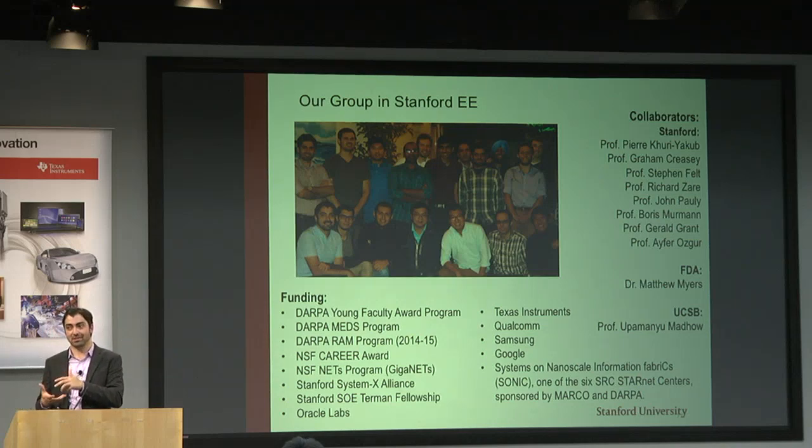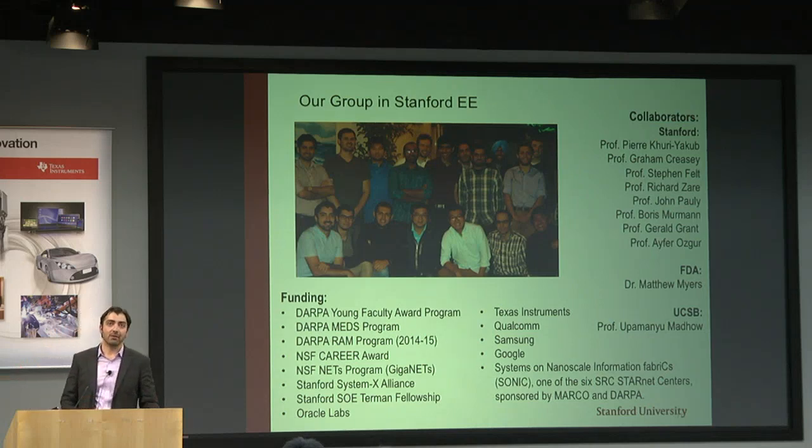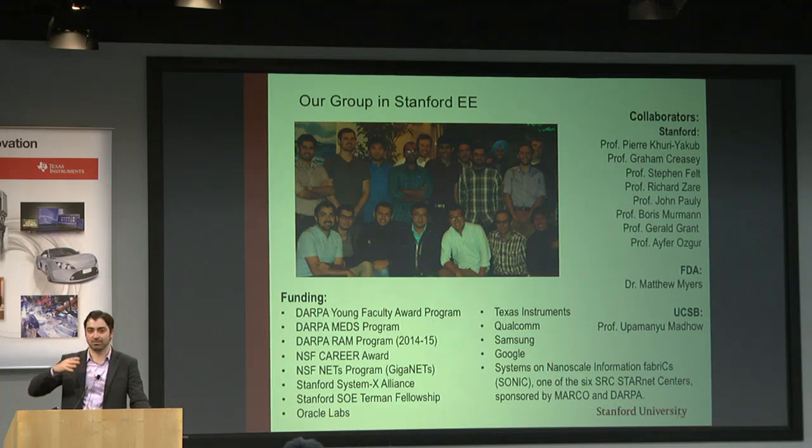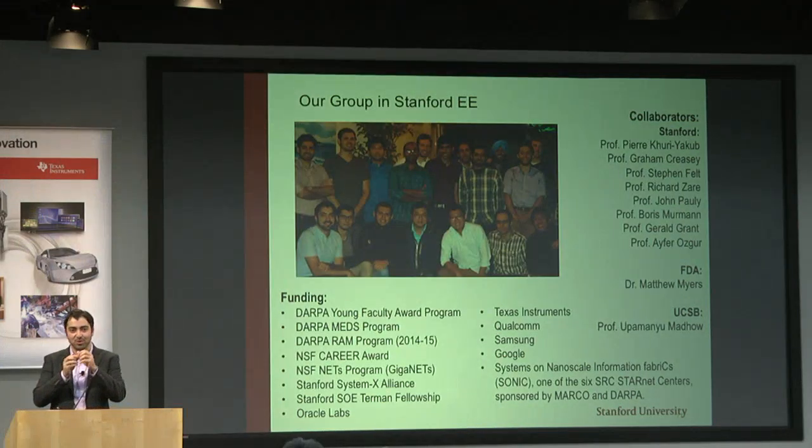When I came to this field originally, I came from a millimeter wave design field. So everything was 100 gigahertz, 50 gigahertz. And I thought, a megahertz will be okay. We don't have to worry about parasitics. Little did I know that the wavelength is still very small. The wavelength being a millimeter means that every 100 microns of trace or packaging or your backing will be a tenth of a wavelength, just like it is at 100 gigahertz. It just happens to be at lower frequency.